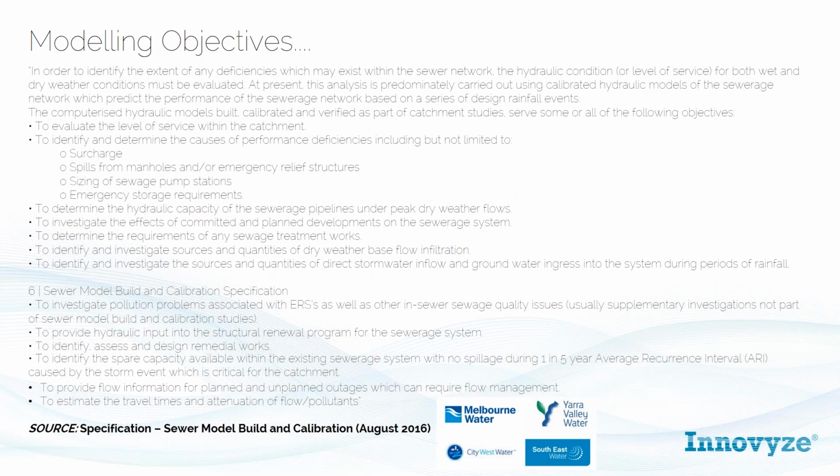So if you want to get better return on the investment you've made with your modeling work, it's best to also revisit the reasons for which you're modeling to begin with and how you can make better use of them as well. From a technological perspective, when you talk about live sewer modeling, models are now entering the operation space where operators are going to be able to run forecasts about what's going to hit the network based on an incoming event. So there are advances in technology where more people can be using them, as well as just going back to the fundamentals.